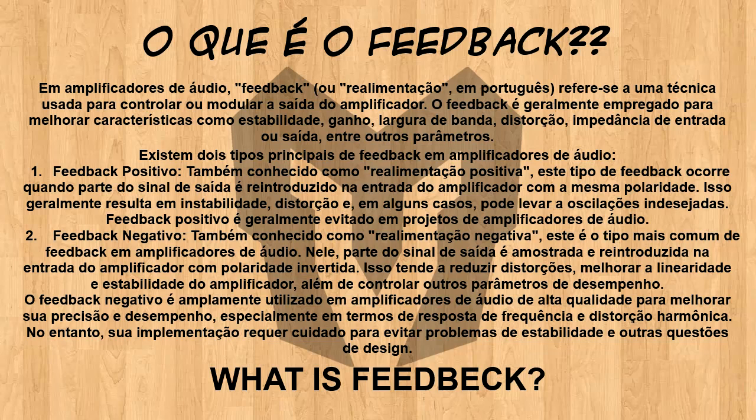Positive feedback is generally avoided in audio amplifier designs. 2. Negative feedback. This is the most common type of feedback in audio amplifiers. In it, part of the output signal is sampled and reintroduced into the amplifier input with inverted polarity. This tends to reduce distortions, improve the linearity and stability of the amplifier, as well as control other performance parameters. Negative feedback is widely used in high-end audio amplifiers to improve their accuracy and performance, especially in terms of frequency response and harmonic distortion. However, its implementation requires care to avoid stability issues and other design issues.